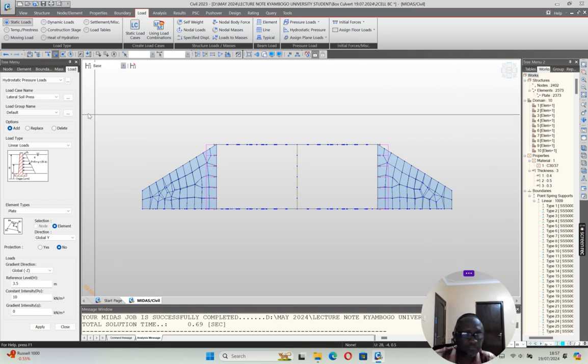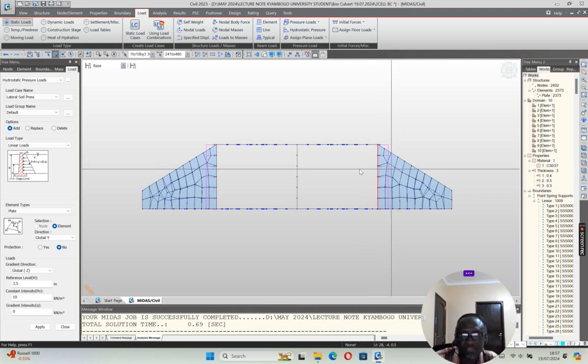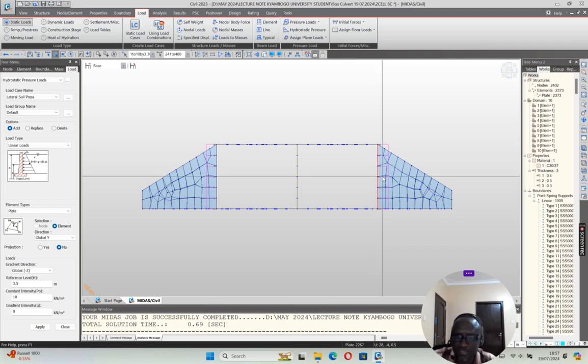I'm done with lateral pressure. Now I'm left with hydrostatic. I can also undo this, and I make sure. Let me assume that the hydrostatic pressure is also all the way up there. That's for calculation. I could do it midway if you have treated your wall very well. So I come in here, my hydrostatic pressure is here. It is that one. This time I'm putting it at 0, and then down, since it is 40 divided by 4, it is 10.